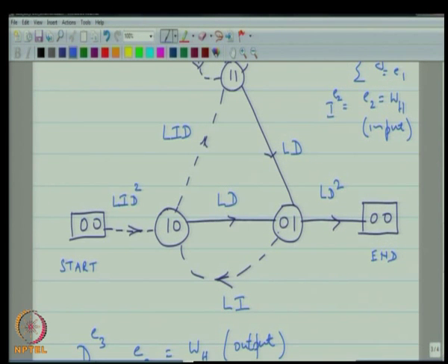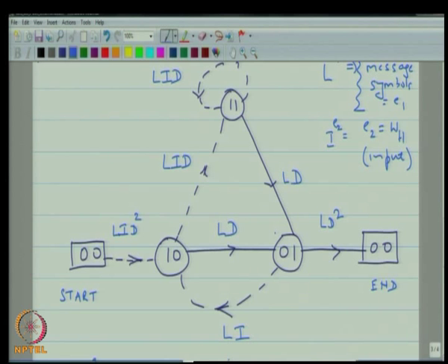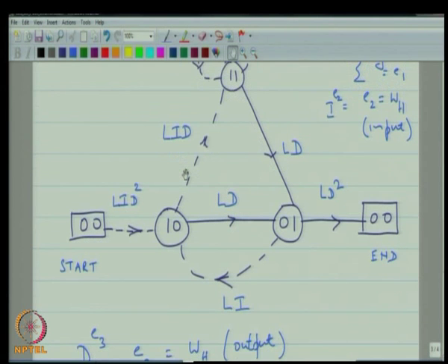Okay. So, for example, this indicates that when going from the 1 0 state to the 1 1 state, you needed one input symbol. That particular input message symbol happened to be 1, and the Hamming weight of the output is 1. Okay, so, that is what this actually represents.